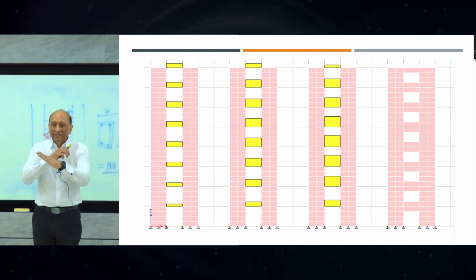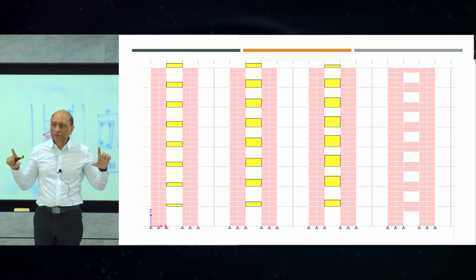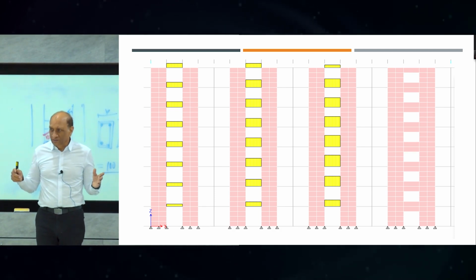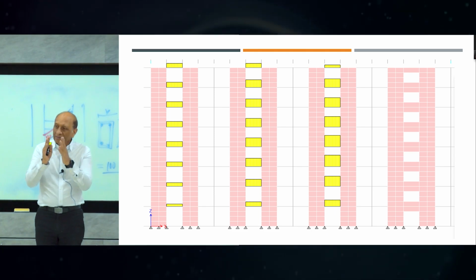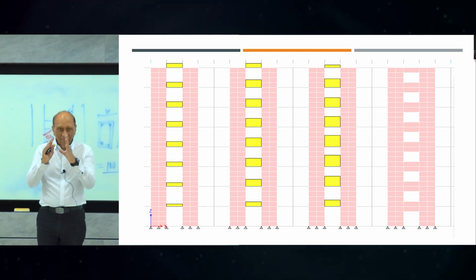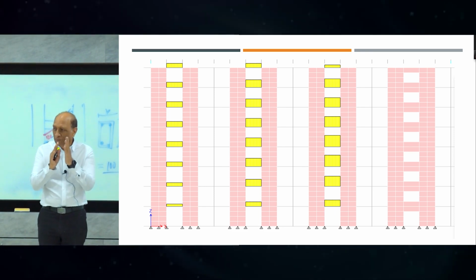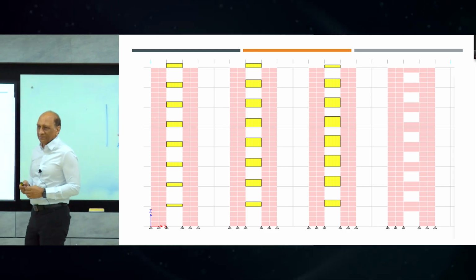And sometimes we put steel bracing there. Sometimes we put the steel beam there because steel is very good in shear. So the coupling beams, if you cannot manage the forces, you put a steel there. Sometimes you put a damper there, a flexible capacity damper, which has the capacity to deform without breaking. So there are a lot of ways that you can use these link beams.